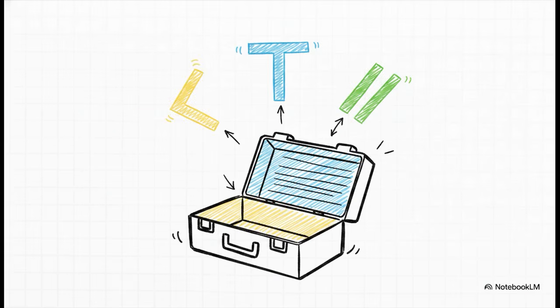To solve the mystery of the tilted shaft, the ASME Y14.5 standard actually gives us exactly 3 tools. We call these the orientation symbols. Now, unlike form tolerances, things like straightness or flatness that just look at a feature all by itself in isolation, orientation tolerances exist specifically to control a relationship. They tell the manufacturer exactly how a feature is angled relative to a datum.